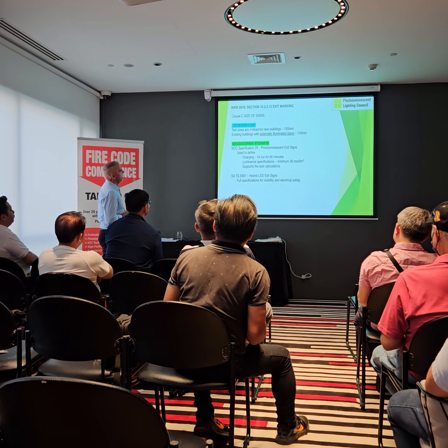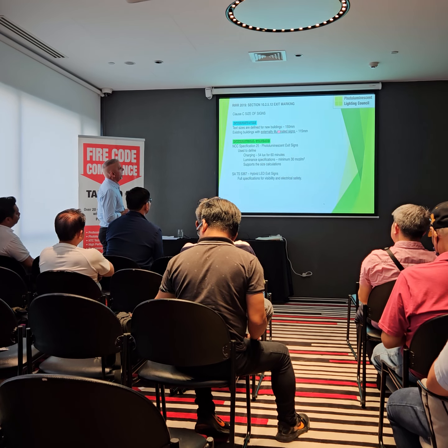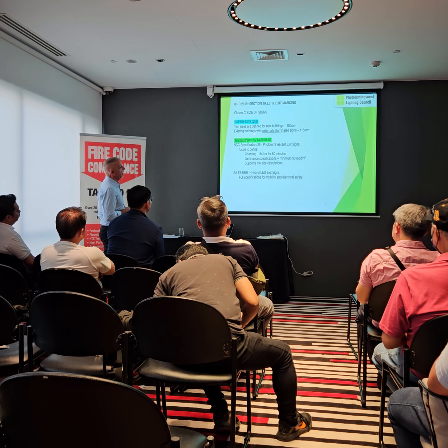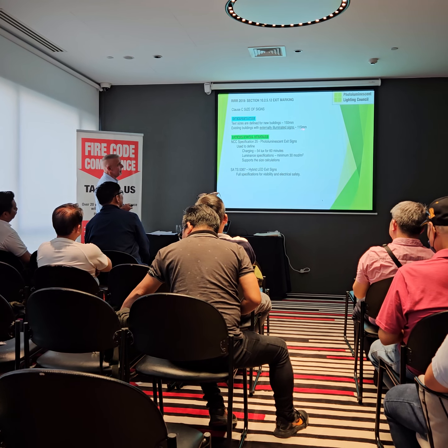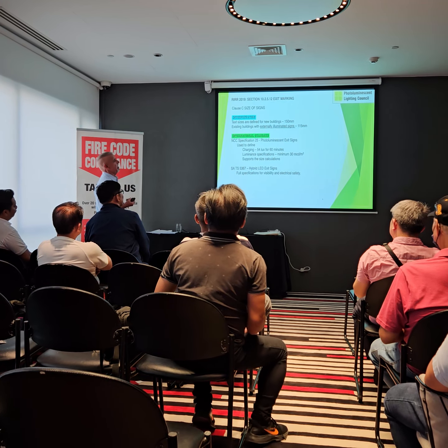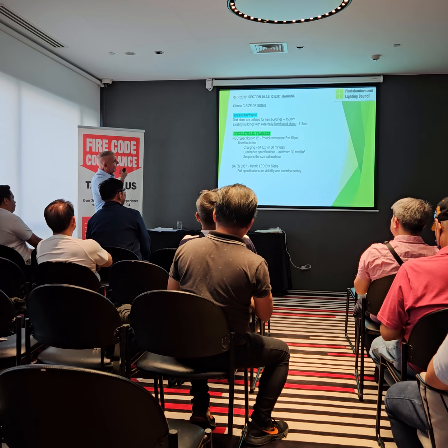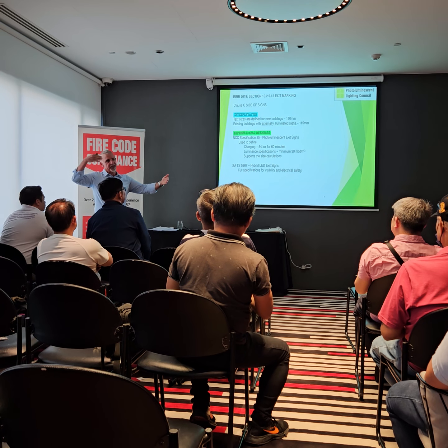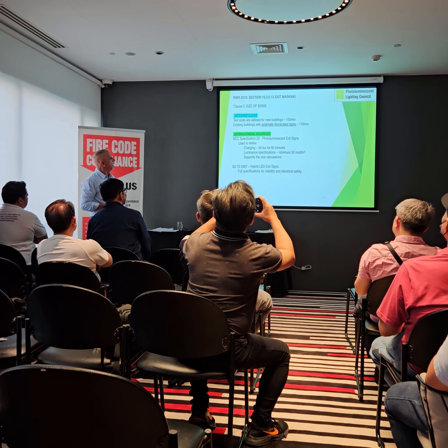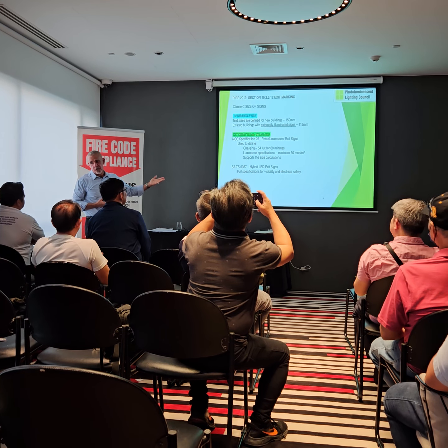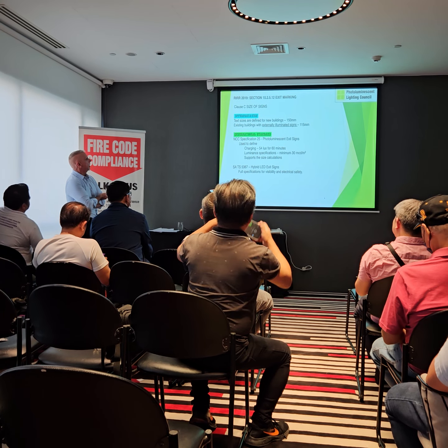It says that you need 150 millimetres in terms of text size, and then it goes into an existing building, and then it says externally illuminated signs can be 115 millimetres. To tell the truth, I don't know where that would have come from. If you're looking at an externally illuminated sign with the emergency light shining on it, I'm not quite sure why it can be smaller. Maybe just because it's in an older building and they're cutting a break for older buildings.